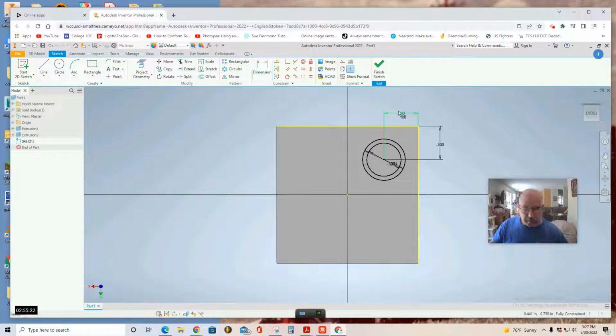Hit the Escape key about 3 times, and to copy these 2 circles, you want to use a marquee, use Control-C to copy it, and then Control-V to paste it. Grab just the center, and then you can pull, and if you're wise, you'll look for that little dash line, which means you're in alignment with the first set of circles.